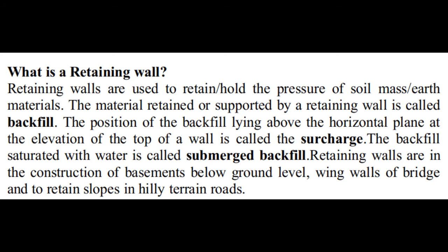Retaining walls are used to retain, from here the name comes, retaining. Retaining walls are used to retain or hold the pressure of the soil mass or the earth material. The material retained or supported by a retaining wall is called backfill. The portion of the backfill lying above the horizontal plane at the elevation of the top of a wall is called surcharge. The backfill saturated with water is called submerged backfill.